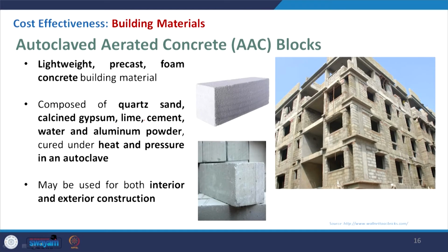Coming to the autoclaved aerated concrete blocks, in this case as I mentioned earlier, this is lightweight, precast and foam concrete. So, basically compared to the concrete block of similar size, this has lighter weight. It is composed of quartz sand, calcined gypsum, lime, cement, water and aluminum powder, and cured under heat and pressure in an autoclave. That is why the name also comes into the picture.